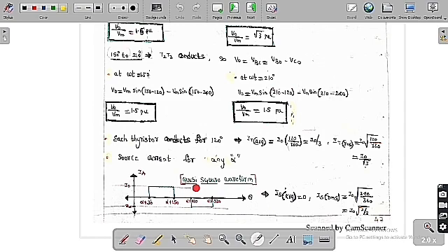So this is called a quasi-square waveform. The source current in this circuit is a quasi-square waveform, and the source current average value is 0, because positive and negative are both present. The RMS value of the source current is I0 into root of 240 by 360 degree, which is 120 plus 120, so we get I0 into root of 2 by 3.